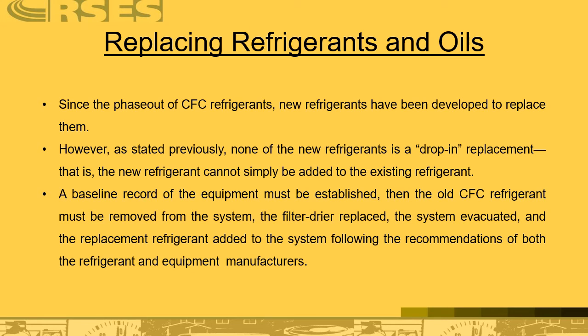There are a few cases where a coil was changed out 5 or 10 years ago and will accept R410A as an alternative refrigerant. I have made those conversions, which are relatively easy, but from an energy efficiency standpoint, from an environmental standpoint, frankly, if you have an old R22 system, it's just better to recover the refrigerant and scrap the equipment. End of discussion.